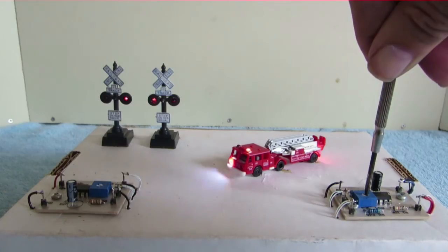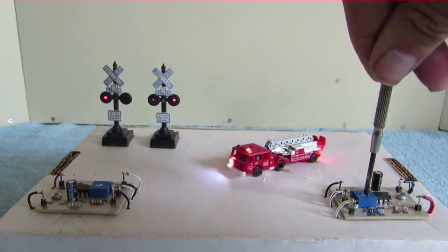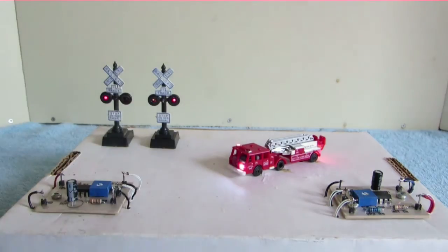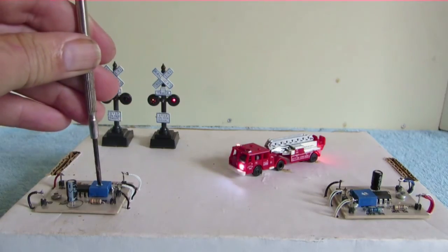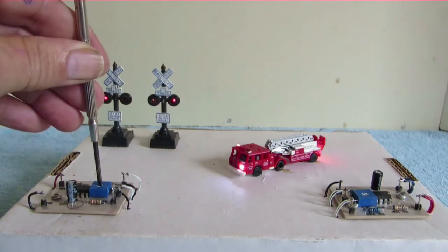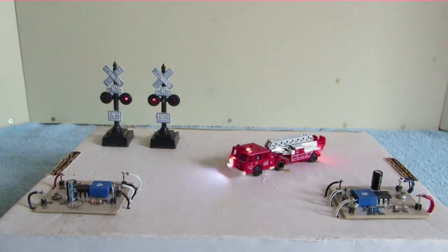To use a 12-volt power supply, you would either have to change the two 470 ohm resistors on the board with maybe something like 1K resistors, or add two 470 ohm resistors to the outputs in series with the LEDs. You can see how I do this on the block diagram I included.